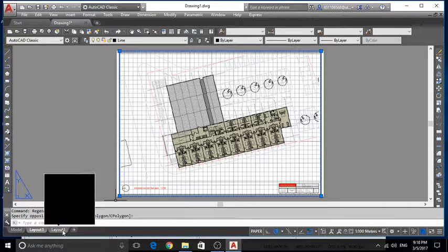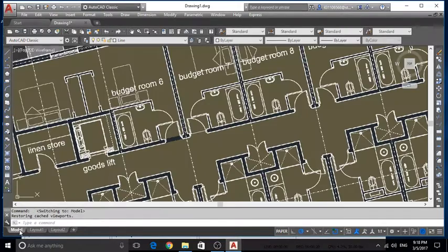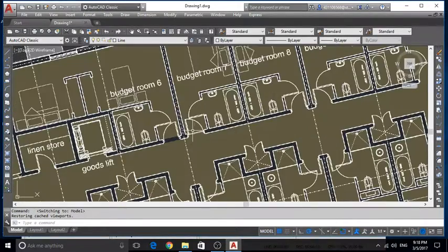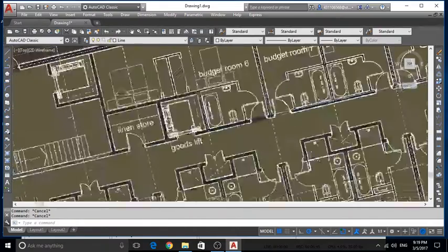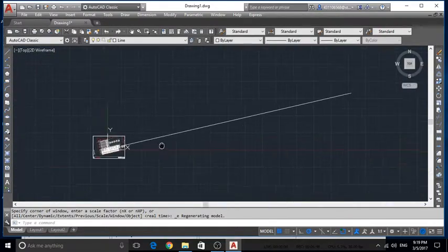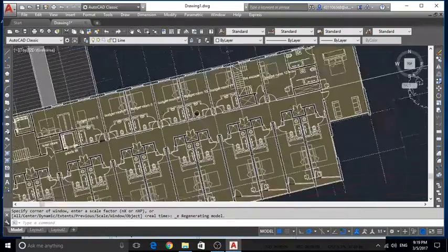Now in the other layout, I must go back actually and rescale the drawing to millimeters. So I'm gonna do the same thing again. I'm just gonna do it fast now. Endpoint to the other endpoint, and I'm just gonna type in 900 for 900 millimeters, which is 90 centimeters. I'm gonna go out and double click. The line is so far away, so I had to do that actually.